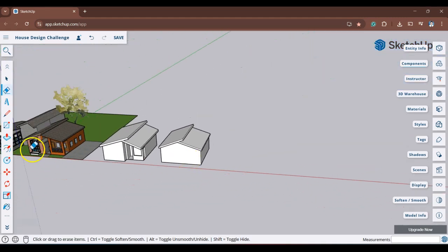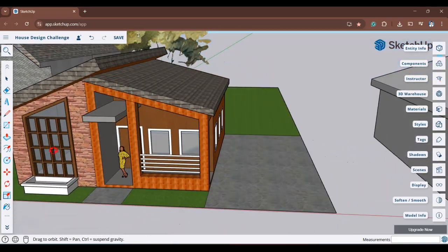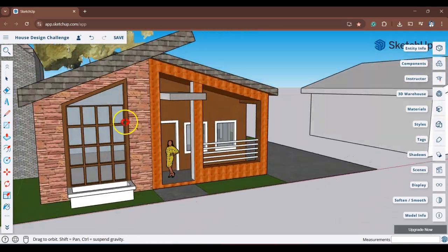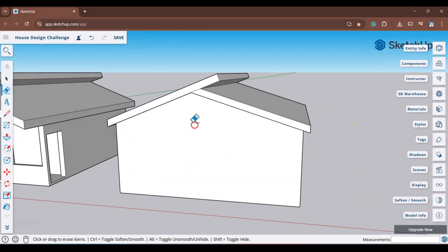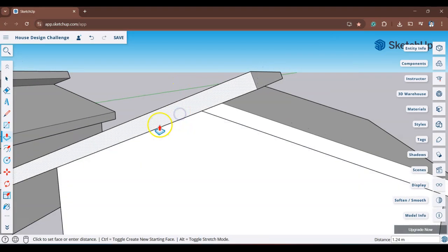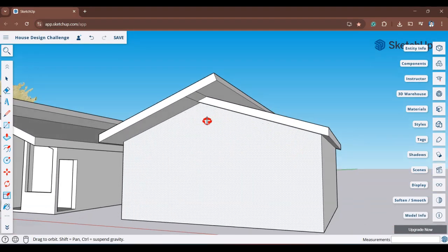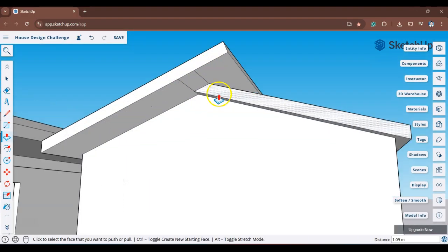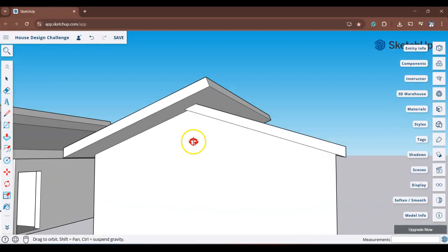Let's look at the example, because now we can just kind of have fun and get creative. The roof is a little staggered there. So I'm going to press P for push pull. Click on this section, bring that out a little bit. There we go. I'm not going to worry about these lines. Let me actually, if I erase them, what happens? Oh, okay, so erase those.